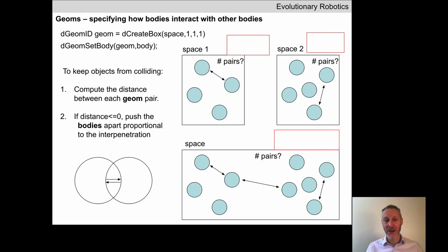If you take the exact same number of links and you distribute them widely, so none of them are anywhere near any other link in the physics engine, you will notice that your physics engine runs much faster. The reason why, as we talked about last time, is it takes quite a while for the physics engine to perform collision detection. Which pair of objects, if any, are in contact with one another? We'll talk about collision resolution in a moment, which is how does the physics engine resolve those collisions? How does it deal with them?